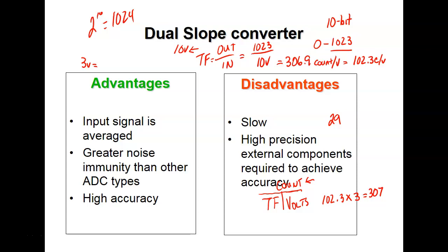You understand? Because we've got the maximum number of counts, and we know what voltage it would be at that maximum. And this is another thing we need to look at too, guys: the problem I had is I've got a 10-bit DAC, a 10-bit digital analog converter inside this PLC right here, and it only recognizes things from 0 to 10 volts.